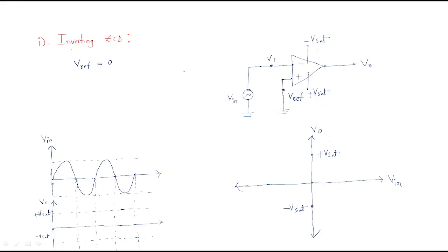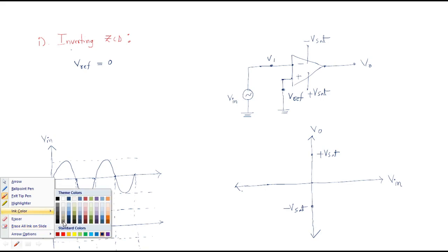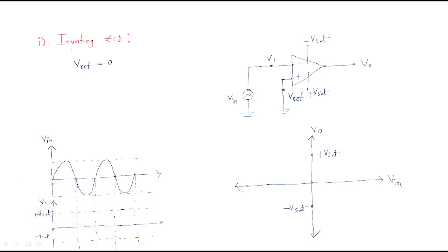We know that. Okay. What happens is, when the input is given to the inverting terminal and the reference voltage is given to the positive terminal, it will generate some output. The output should be a negative value. The output is like this. It shows some negative value.